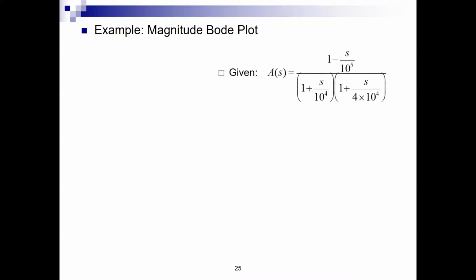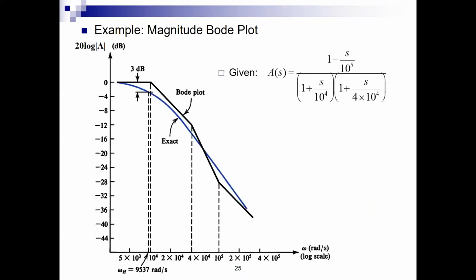Okay, let us see what he showed here in the drawing of the Bode plot. For the Bode plot, irrespective of how far my omega 1 is from omega 2 and the zero, I would still draw the Bode plot. If he tells me that it is 1 over (1 plus s over 10 to the 4) to the power 2, what do I do with this? I have two poles in the same location. What will happen here? I ignore one of them? No. I will have a response.